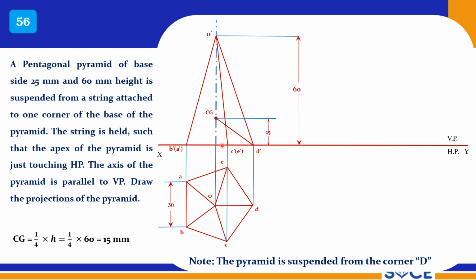You have this line. You have this reference line. Now to this line you set the drafter parallel to this line. It will be very simple if you follow this procedure. Now you draw a thin line 90 degrees to this line. Students, when you draw the thin line, that should touch this O, apex. It is only for reference. You are not going to keep that line as thick line. It is a thin line, it has no meaning, but that is useful to reproduce here.